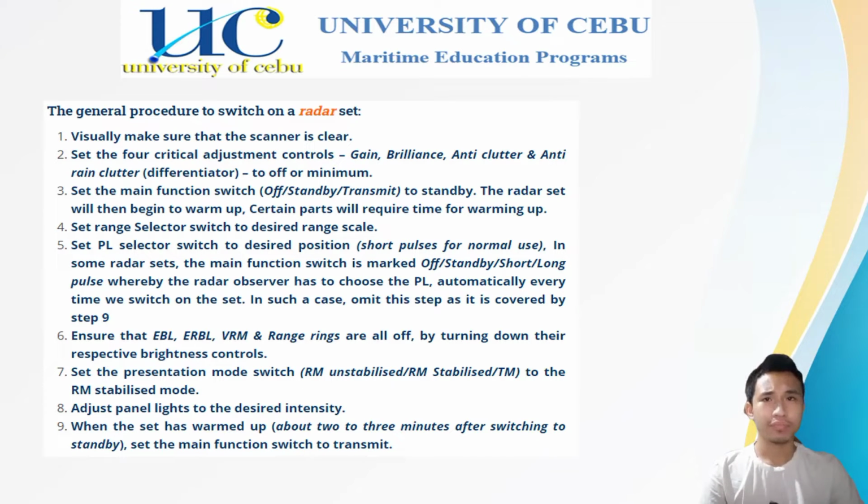The general procedure to switch on a radar set. First, visually make sure that the scanner is clear. Second, set the four critical adjustment controls: gain, brilliance, anti-clutter, and anti-rain clutter differentiator to off or minimum. It is important to set the gain, brilliance, anti-clutter, and anti-rain clutter properly, because